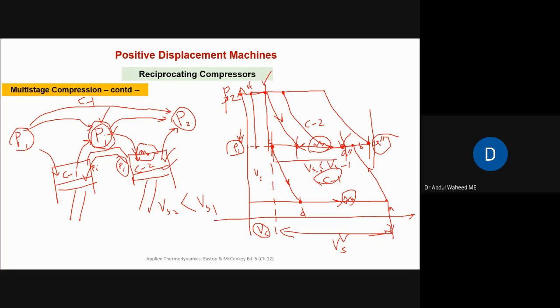Because second stage का जो compressor है उसका design is different from the low stage compressor, because this compressor is compressing a different volume of gas. Same mass, but different volume. Because यहाँ volume definitely already increase हो चुका है. So that's why the design, the size of that compressor is normally smaller than C1. Why smaller? Because already volume is reduced. Right. So to compensate for the same mass, its volume should also be reduced.